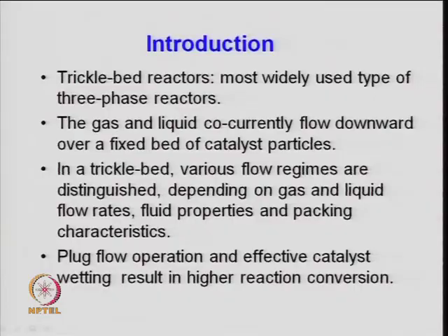residence time distribution in a trickle bed reactor. So, trickle bed reactor parameters need to be studied, hydrodynamic studies need to be done, and the actual reactor performance, conversion and efficiency also need to be tested. So, plug flow operation can be achieved in the trickle bed reactor, and effective wetting of the catalyst results in a higher reaction conversion. So, one needs to try the RTD, and based on the RTD operation, you calculate or measure the dispersion number D upon UL, or the Peclet number, and then you correlate these numbers.